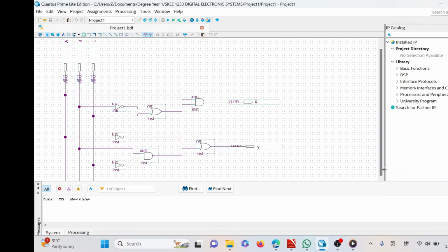We will now describe the basic gate logic circuit. Input B enters the NOT gate and it will produce an output of B bar. Then the OR gate will receive inputs B bar and C and generate an output of B bar plus C. The last AND gate will receive inputs A and (B bar plus C). The final minimum expression for output X is A(B bar plus C).